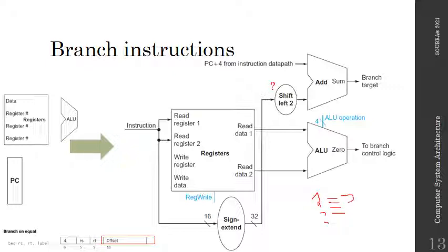So normally PC plus 4 will get you to the very next instruction. But imagine that in case of a branch, you're going to go ahead and reach somewhere. So with 16 bits, if I'm using byte addressing, you can see that you're limited. The distance is limited because each 4 bytes will be only one instruction away. But what if I wanted to reach even further? So I want to branch to something that is far, not that near. So what would be the solution?